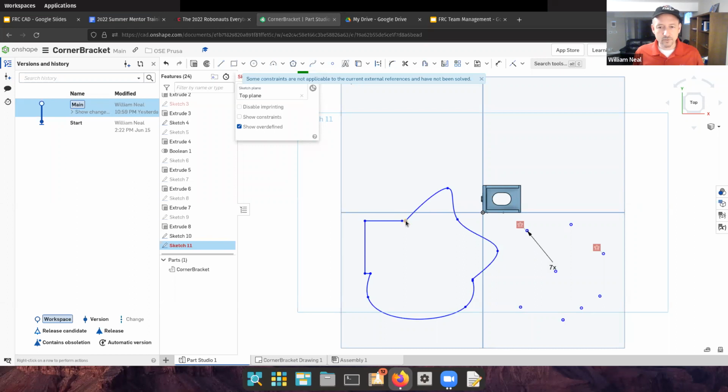So what may I do? This is the point at which we may start adding constraints to our drawing. So we create the shape of our drawing. We modify it a little with overall modifications, but then we lock our drawing down to a specific design and dimension using our dimensions and constraints here. So this first constraint that comes up is called coincident.